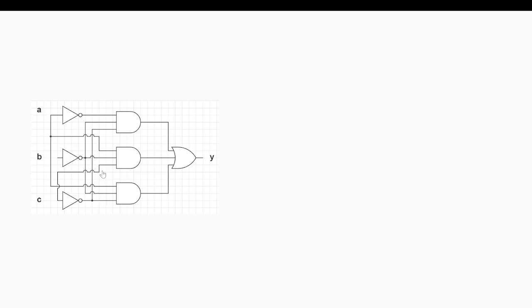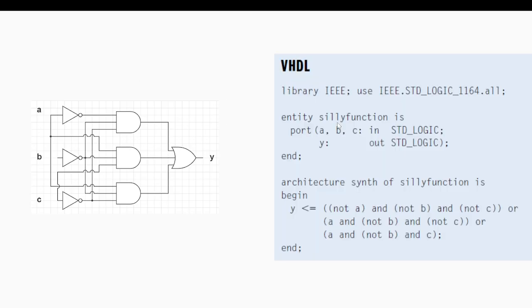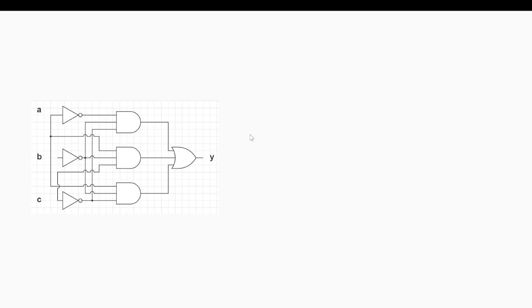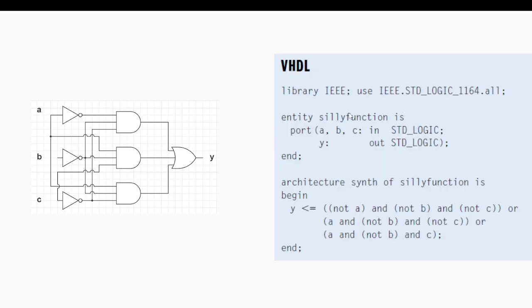So that's another good practice for when we want to implement this design. The VHDL entity for that can look like this, but for this particular course, I rather suggest not to use these libraries. You can implement it just like this, but rather than using standard logic, simply use bit, as we did in our previous example.